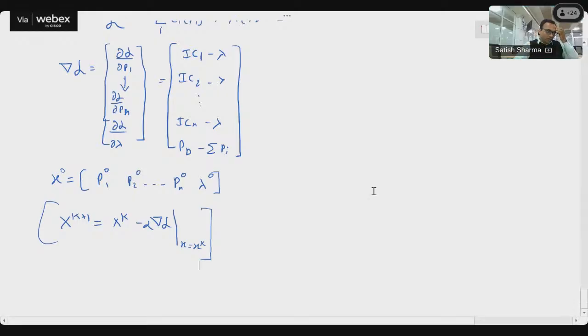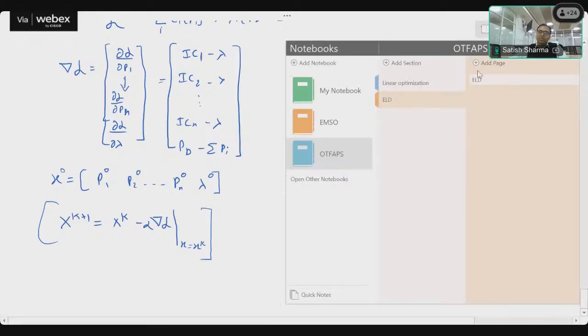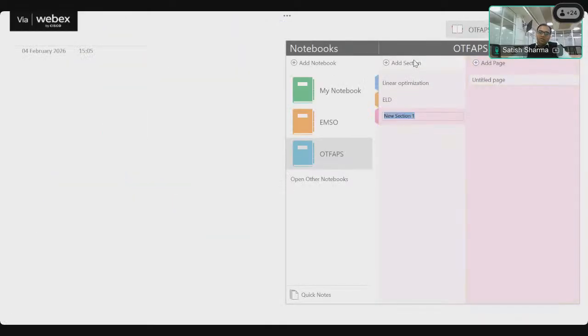Okay, so if we have no doubts, we will move to another segment, basically how we can solve it. So far, we have considered that we are trying to minimize the cost of the generators to satisfy a particular schedule. This is our economic load dispatch. Now another problem is if we want to incorporate the power flows. In that case, what will happen?